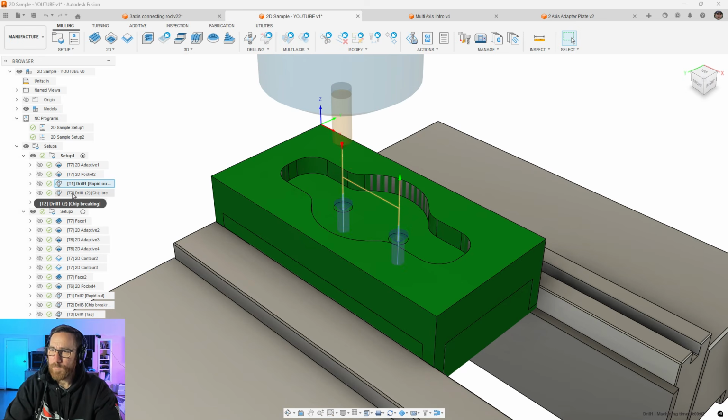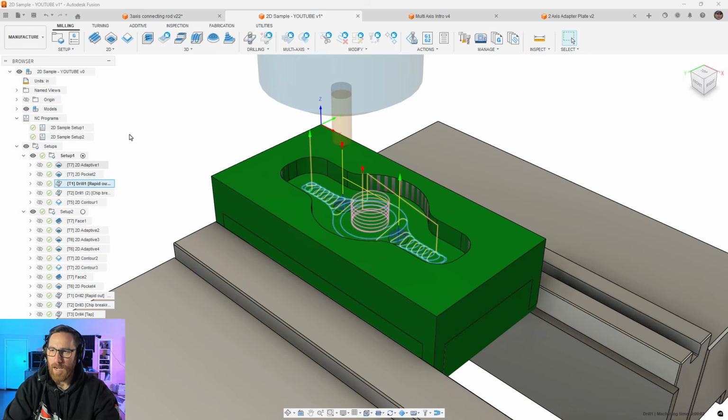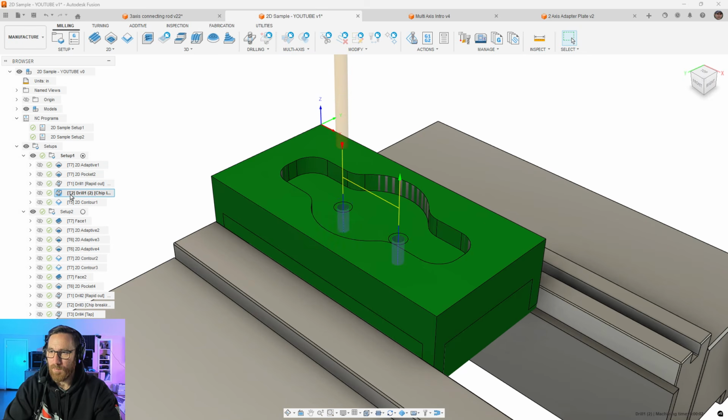When we're drilling holes, typically you want a nice machined surface, and then you will spot drill the hole. And again, there are rules that you follow, things about the actual tip angle of the spot drill and having that be different than the actual drill bit. And if we're tapping, or if we're boring holes, then there'll be certain requirements that we follow there as well.